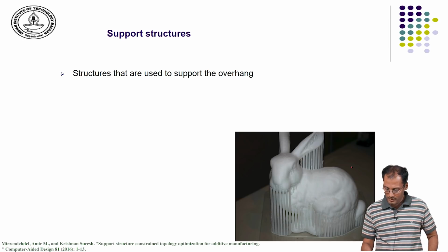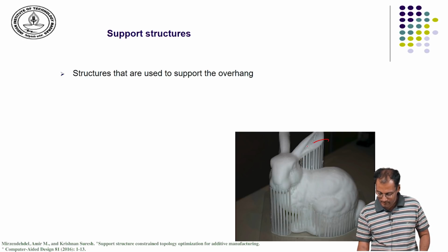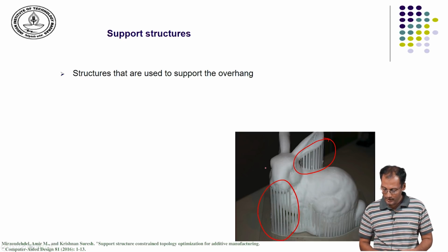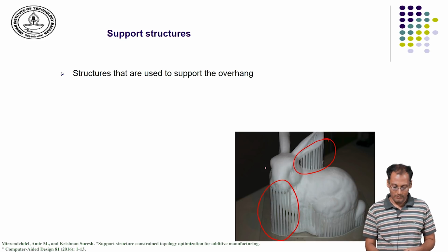The support structures, as I have mentioned, cause surface aberration as well as increase the build time, and they also in turn depend upon the part build orientation.